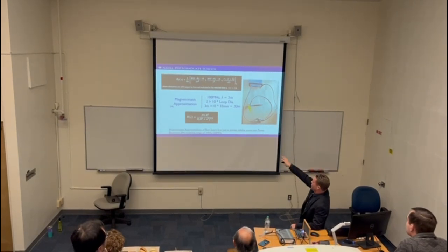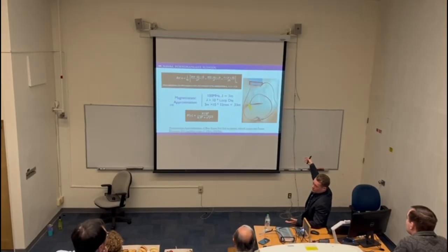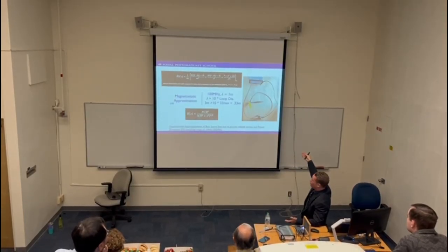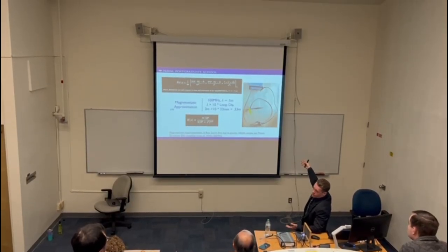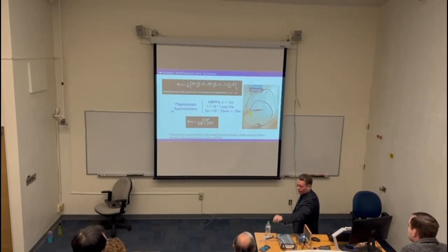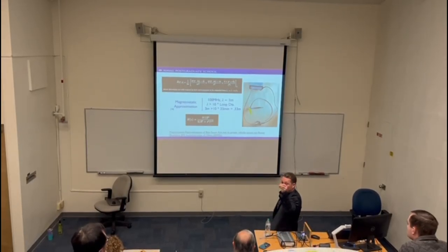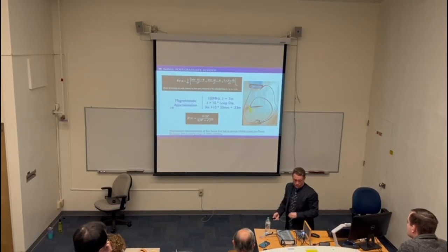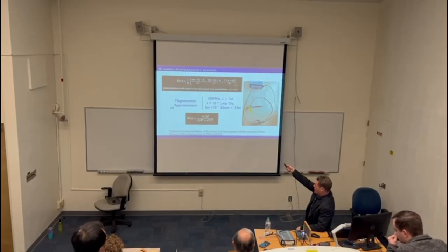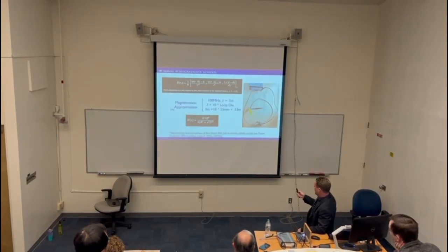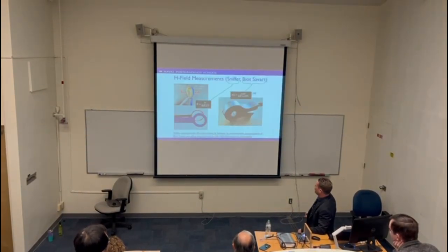as long as the assumptions are correct. I'm saying that the highest frequency I'm working at is 100 megahertz, the wavelength of that is 3 meters. Well, 3 meters is much, much bigger than, say, for instance, this, right? So the assumption should hold. And so let's try it. That's the Biot-Savart law for the current in a coil.